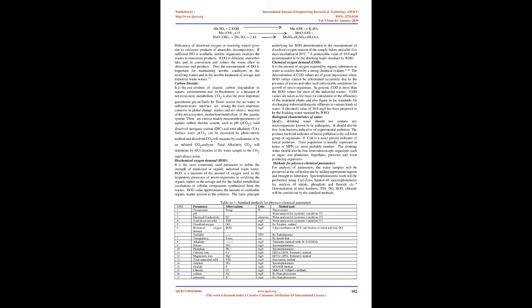This iodine is titrated by standard sodium thiosulfate solution using starch as an indicator. Deficiency of dissolved oxygen in receiving waters gives rise to odoriferous products of anaerobic decomposition. If sufficient DO is available, aerobic organisms oxidize the wastes to innocuous products. If DO is deficient, anaerobes take part in conversion and reduce the waste, often to obnoxious end products. Thus the measurement of DO is important for maintaining aerobic conditions in the receiving waters and in the aerobic treatment of sewage and industrial waste waters.